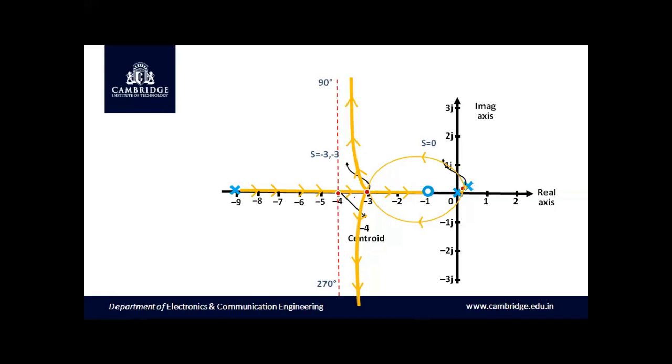So let me repeat once again. When k equal to 0, we can see the location of poles and zeros, that is, the starting point of the poles and zeros will be exactly at s equal to 0, 0, minus 9. When k increases, we can see the movement of these poles in the region of the root locus, and they try to intersect at a single point, which indicates the location of triple roots for the solution of the breakaway point at s equal to minus 3.